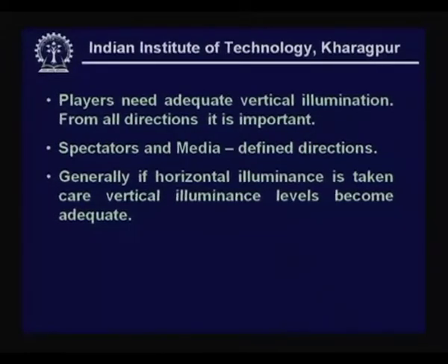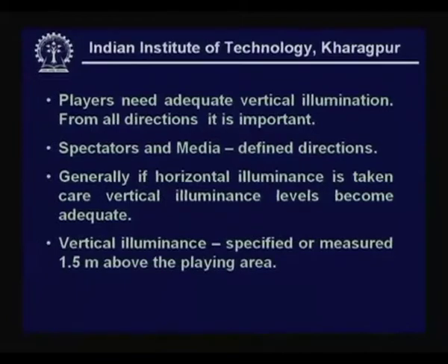But it is observed that if horizontal illuminance on the play area is taken care of, the vertical illuminance levels become adequate, considering the recommended practices of mounting the lamps as per the CIE recommendations. So, what it means? Horizontal illuminance no doubt plays as a background, but vertical illuminance is necessary from the point of view of a good game, and if horizontal illuminance is taken care of, vertical illuminance levels become equally adequate.